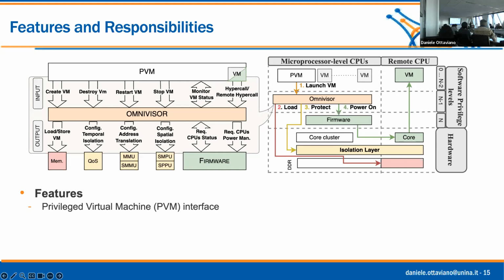So the very goal of the Omnivisor is to say, okay, you can run software in this case on a remote processor, but somebody has to say that this code must not access the other virtual machine, the virtual machine memory, for example. So you're creating a sort of isolation layer to block these cores from messing with the system. Now, I guess in the case where it's an FPGA or software, you're still using the IOMMU to do that. Okay. Yeah, you can use the IOMMU to protect.